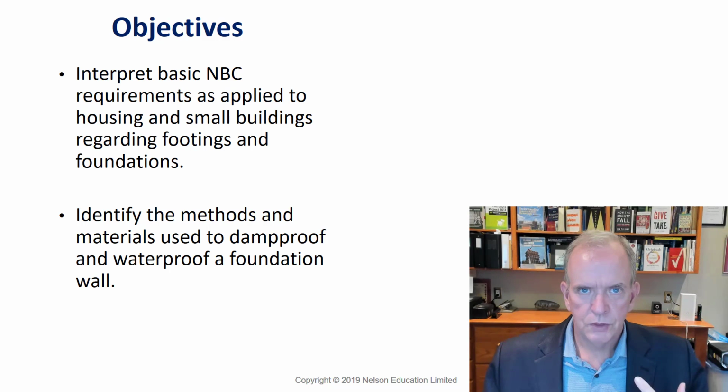National Building Code, as you recall, that's the national standard for Canada. And Ontario Building Code takes from that standard, has its own unique requirements for Ontario, and goes from there. Although I will say I don't think there's any significant differences between Part 9 of the NBC and OBC when we start talking about footings and foundations. There's structural elements, and there's not massive changes from that respect for us.